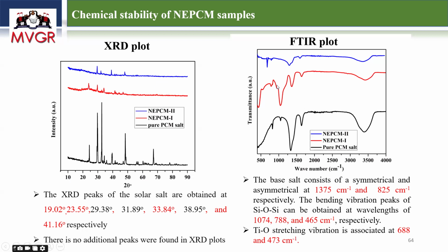This silicon oxide group will be available. These are the pure PCM peaks, and the same peaks will be available here also. Apart from that, an extra new peak appears, which is silicon oxide. So silicon oxide is perfectly coated here, and titanium oxide is perfectly coated here. From the XRD plots and the FTIR plots, it is confirmed that there is no chemical disturbance after doing that encapsulation.